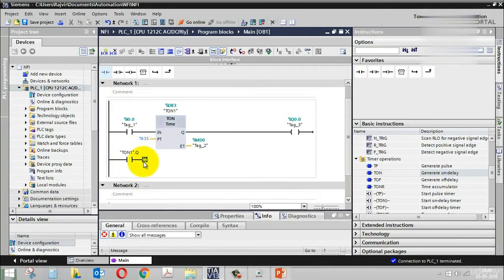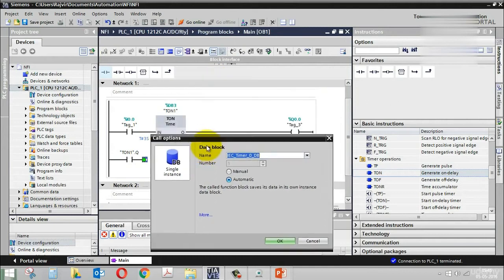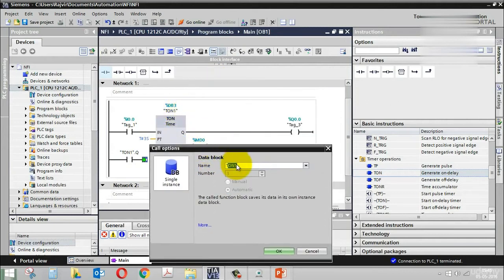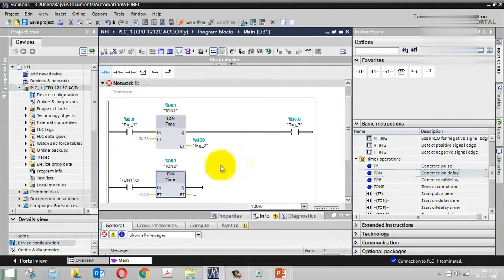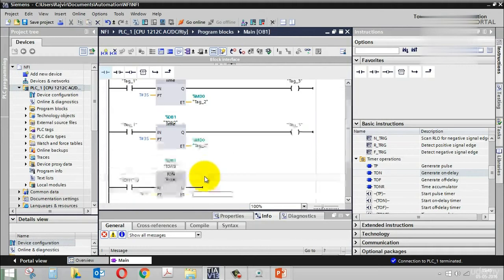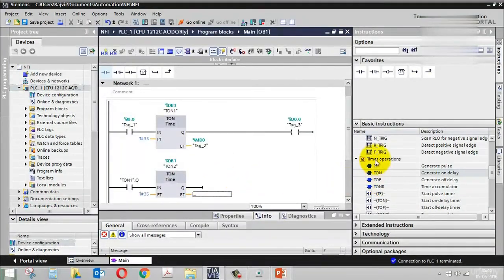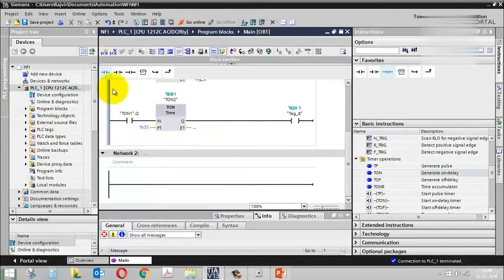Now this is going to generate a signal for another timer. So I'll take TON here. Another data block, so I will take TON2 this time to make it look easier. Time is 3 seconds. I don't want the estimated time here. Okay, now Q, another output, that will be Q0.1. Okay, now comes another ladder.